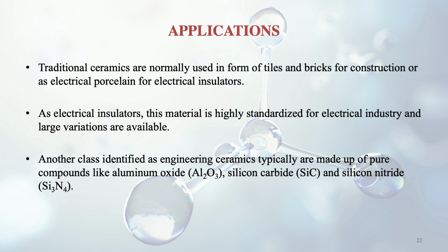Another class, identified as engineering ceramics, is typically made up of pure compounds like aluminum oxide Al2O3, silicon carbide SiC, and silicon nitride, that is Si3N4, the chemical formulas.